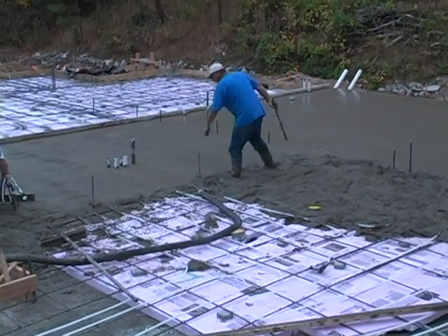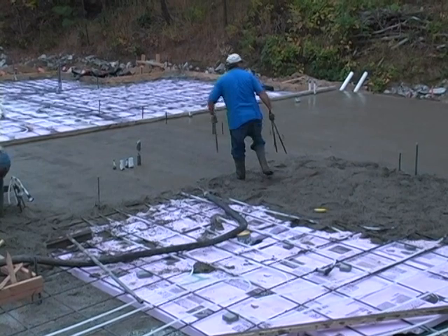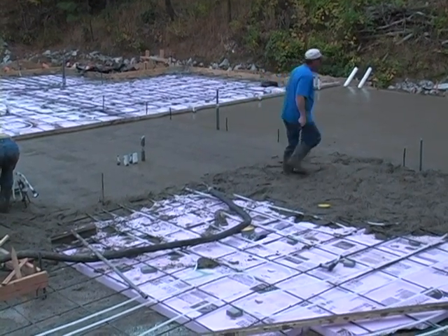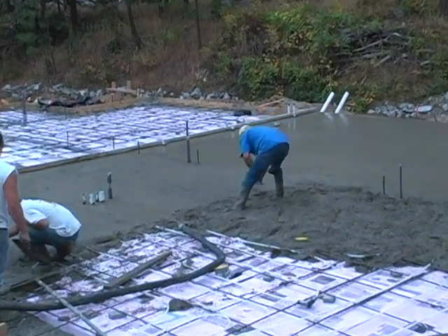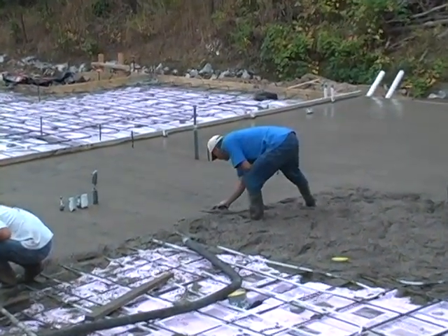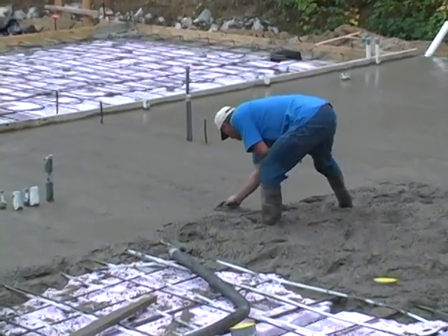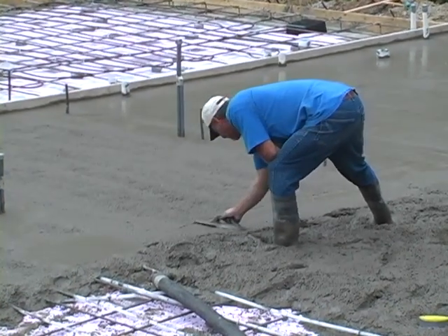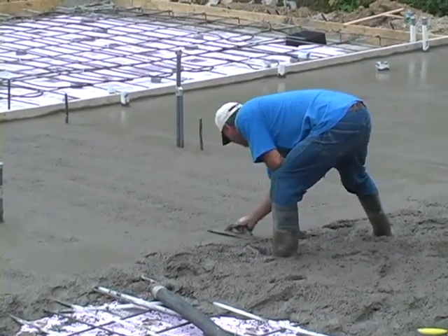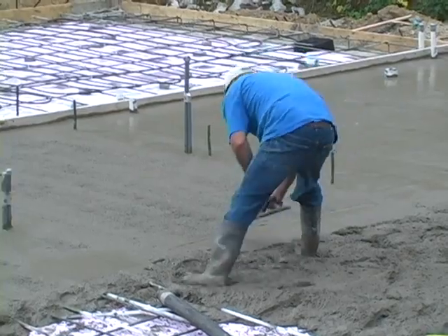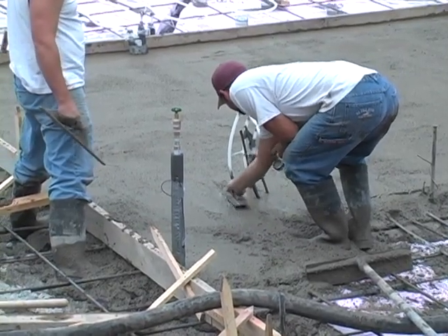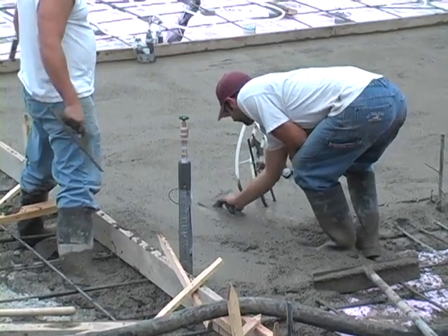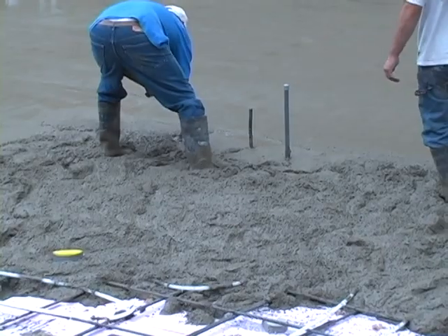So then when we pull the stakes out that the screed posts were sitting on, we can then clean up that entire line and create something that we can actually use, like I said before, as our screed. So again, we'll run a mag trowel up and down on this and flatten it out and get this as level as possible, because this will be where we set our screed board as we move back towards the right of the frame. We'll use that screed board to run right on top of that concrete surface,